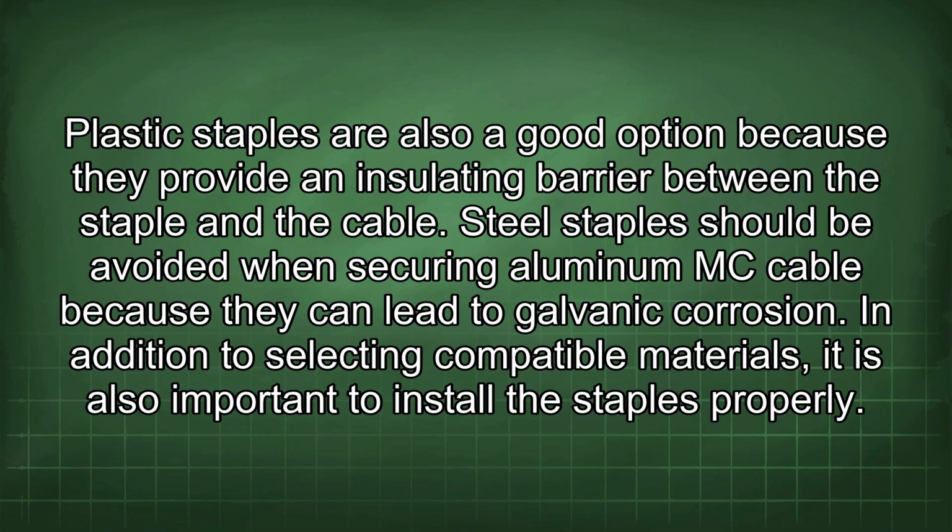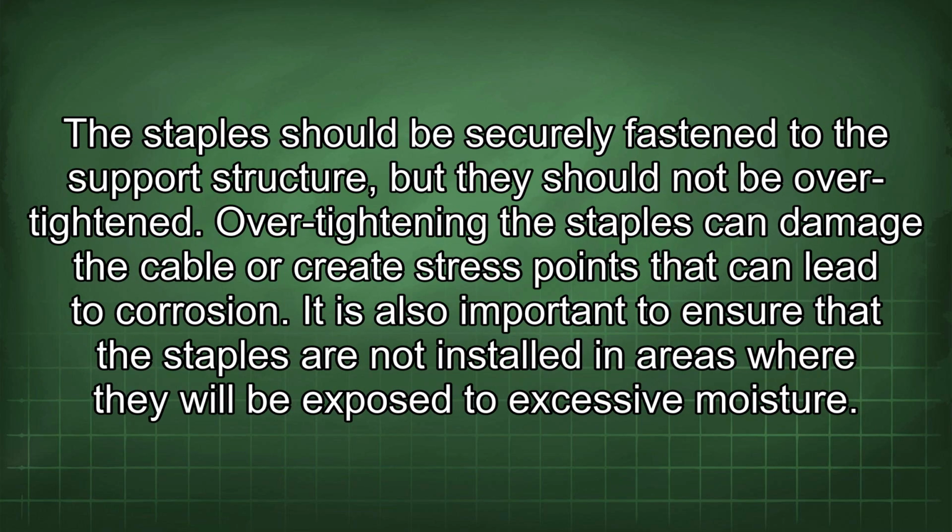In addition to selecting compatible materials, it is also important to install the staples properly. The staples should be securely fastened to the support structure, but they should not be over-tightened. Over-tightening the staples can damage the cable or create stress points that can lead to corrosion. It is also important to ensure that the staples are not installed in areas where they will be exposed to excessive moisture.